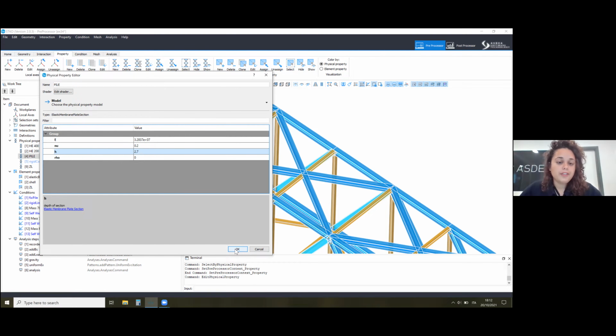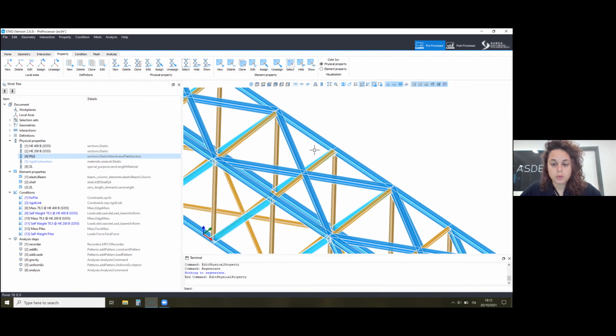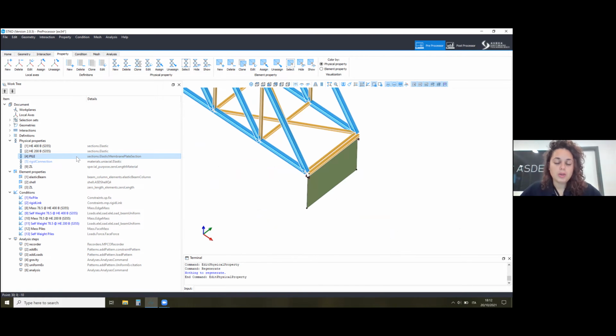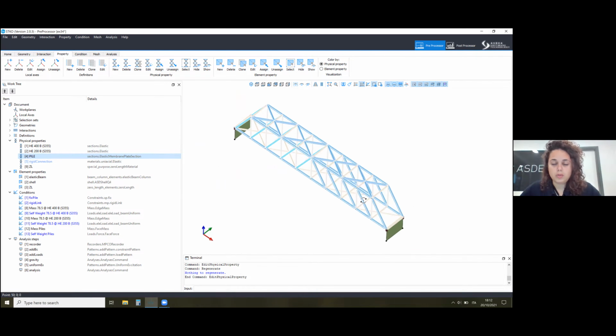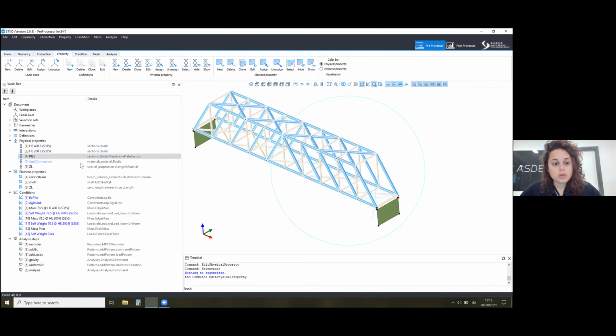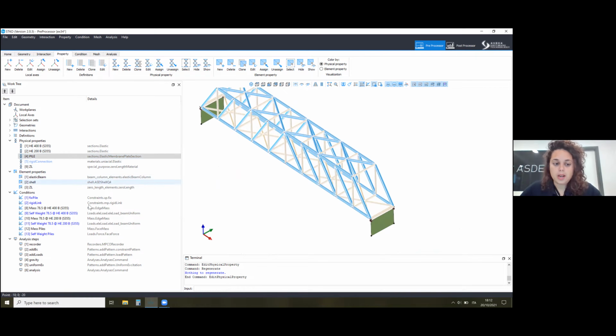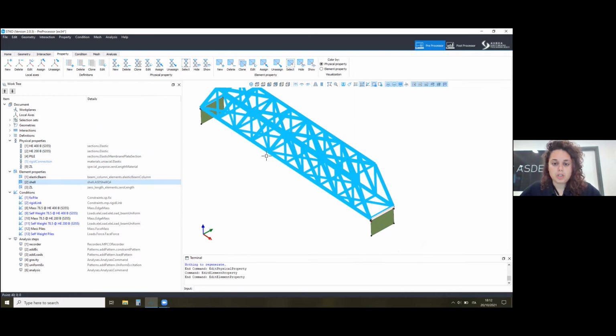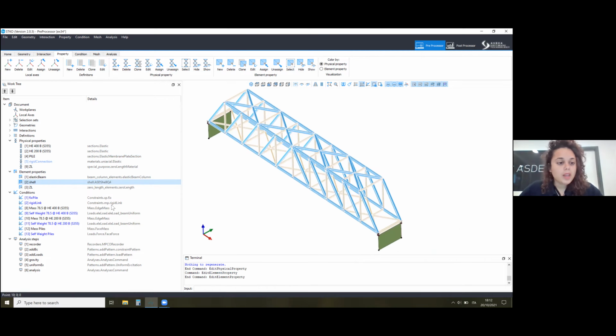And like this, we have an elastic membrane plate section for these faces as supports. This is just the basics of how you can use a face, so a shell or a plate element, inside STKO. I know that we talked just about 3D frame structures, but just for you to be introduced to it, you can use this one and the shell as the ShellMITC4 element. And you have to remember to assign specific mesh control. I will tell you later on.